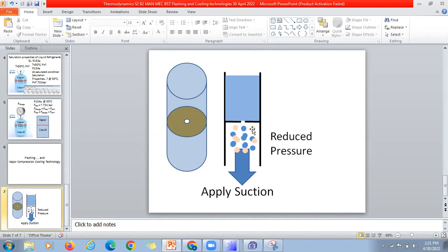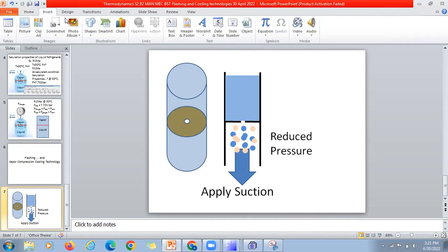So these gas molecules: before turning to gas, it is liquid above this flow restriction, but once passed through here, it turns into gas. So this is the point. I believe you can understand this. This is the flashing.